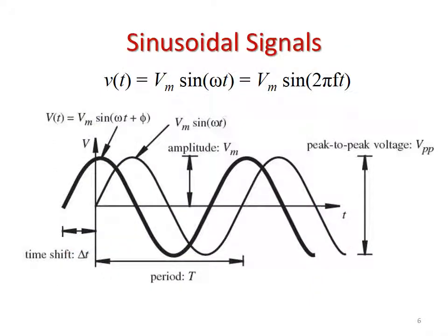Again, we have the same sinusoidal signal here. We have our 2 pi f. Vm is our amplitude, and we have our phase value there. If we go back to the previous slide, you can see that the magnitude we got, c equals the square root of a squared plus b squared, translates into your amplitude. The phase angle, which is the arctan of b over a, translates into the phase. That's how we can pull one of those previous equations into the wave equation here.